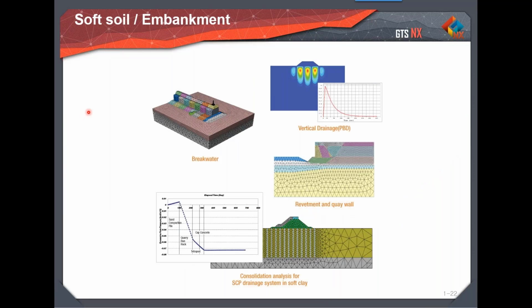And the next and last application is the soft soil and embankment. So let's say you're dealing with a road infrastructure or roadways, and you face a clay soil, and the London clay, as you know, is one of the most interesting soils being studied by many researchers around the world. So London clay kind of things can easily be simulated, and then you can go for a PVD technique, or you can go for sand compaction piles or gravel compaction piles.